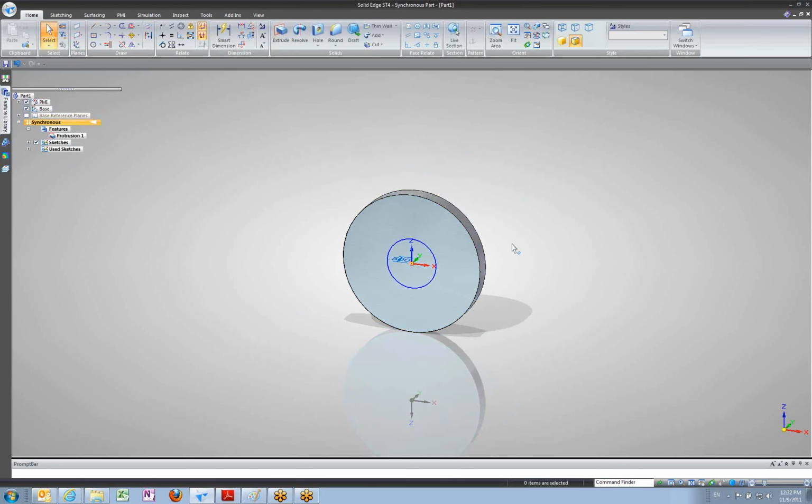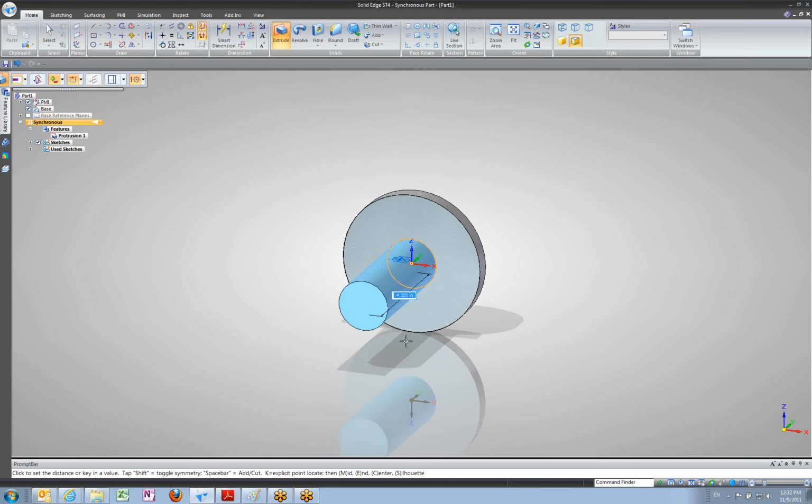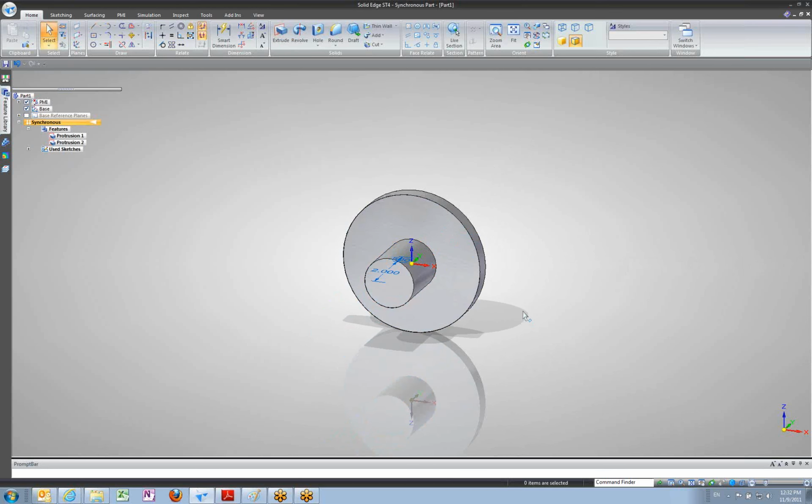So now I've got a 3D body. You can see that I've taken that outer region and extruded it out. I still have a region now on the face of this part. And I'm going to click that and do the exact same thing. Click it once, and then click once to select that arrow and extrude that out. Notice if I push in, it's going to cut that material away. But if I pull out, it will extrude that material out. And again, I'm going to make that 2 inches long. Okay, so we've got the start of a very basic part here.